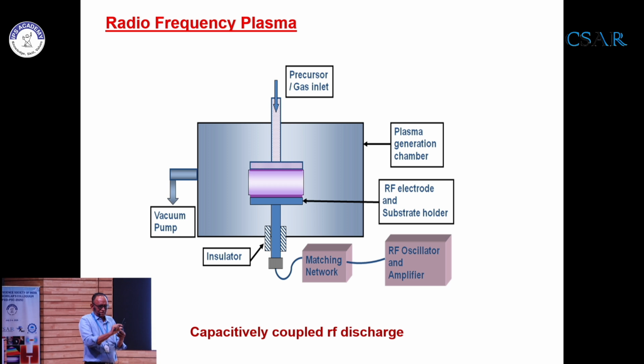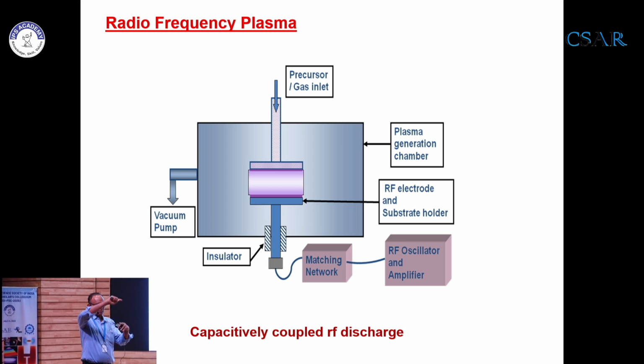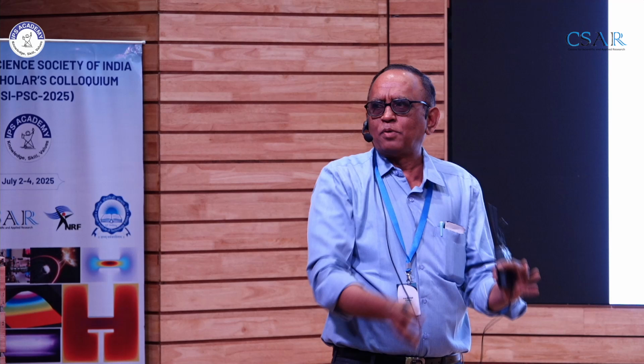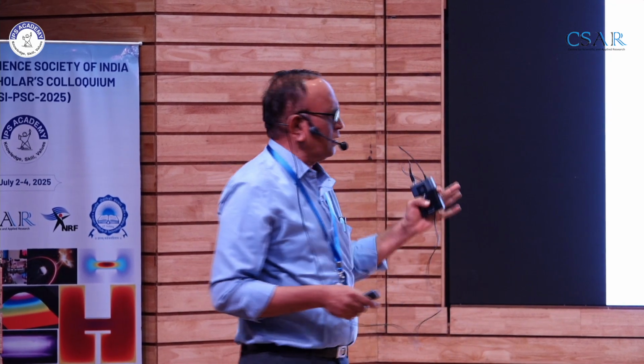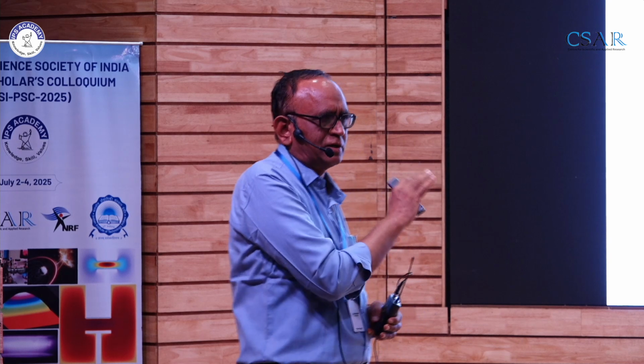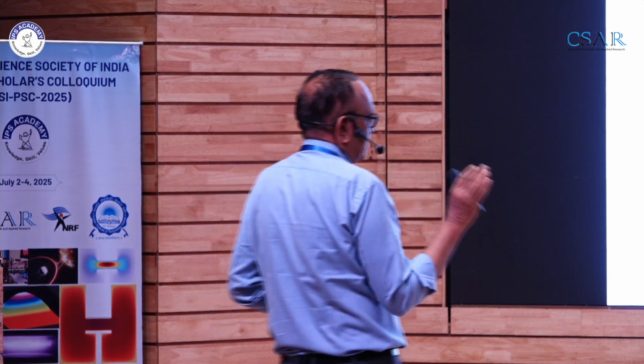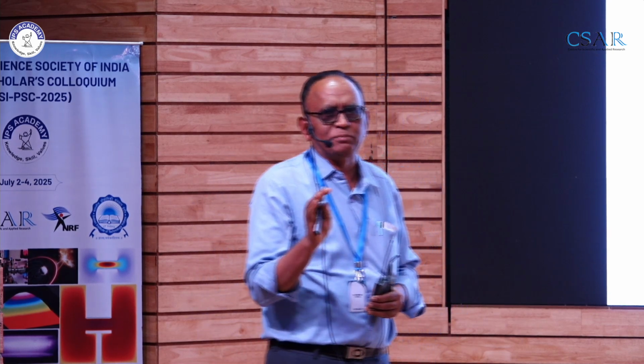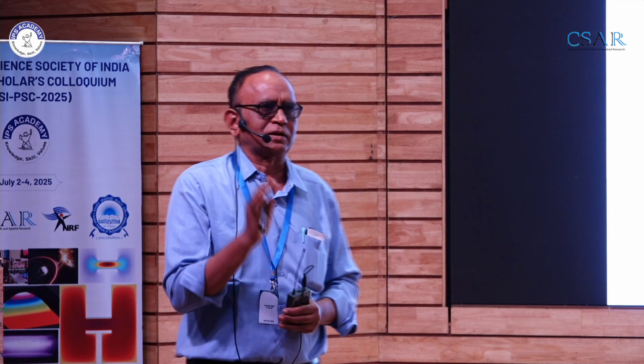And again, when the field is on the rising portion, the electron will continue gaining acceleration, but in that time it has undergone so many collisions that even if it is in the falling region of the cycle, maybe because of the collision, it is in the favorable direction again for gaining energy. I will not go through the mathematics, but that formula is written here. So the energy gained by the electron per unit volume of the medium is proportional to the square of the electric field strength.